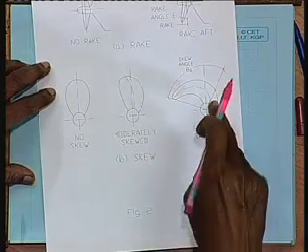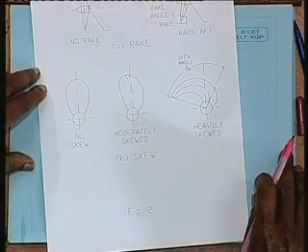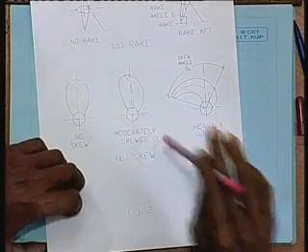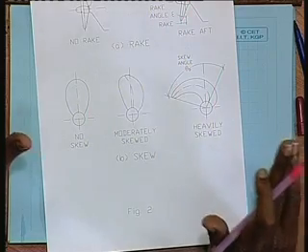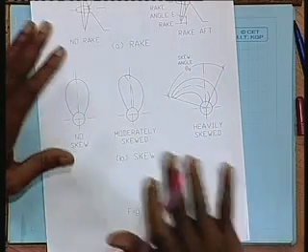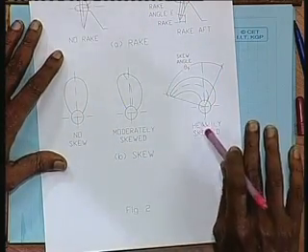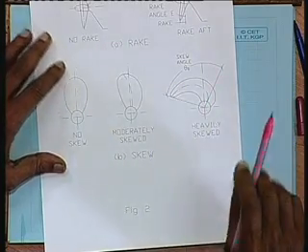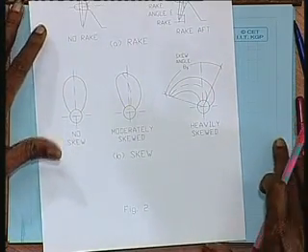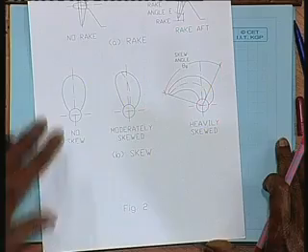Why is a propeller blade skewed? There should be some reason why we do this, particularly heavily skewed propellers. One can appreciate that moderately skewed propellers can be designed to suit the geometry and other constraints. But why heavily skewed propellers? It has been found that heavily skewed propellers can adapt themselves to varied wake field or varied velocity field much better than normal propellers.